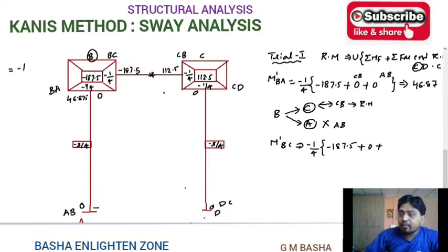For BC, again displacement factors, we have to look in the beam connecting members, columns. So there will be two members connecting to the BC joint, that is at B. So you can look only BA, not this CD. And I already told you, displacement factor for the beam always will be 0. Therefore for BC also you will get the same value, that is 0, which we are looking for the AB. So if you simplify, you will get the same value.